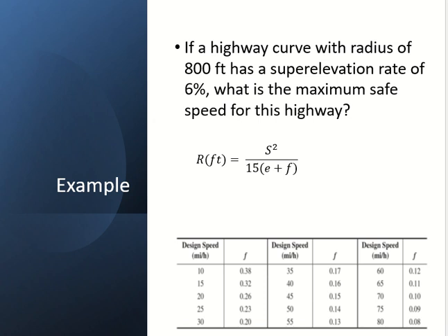Okay, so just one point for the previous question as well as this one or any other. I'm mentioning that the conversion factors are already part of the equation. So don't try to convert it yourself, that the time should be in this and the speed should be in this. This is already done if you're using the equation with the factor there. Secondly, what is the question asking? Give us speed. And we have a factor here, side friction, which also depends upon speed.